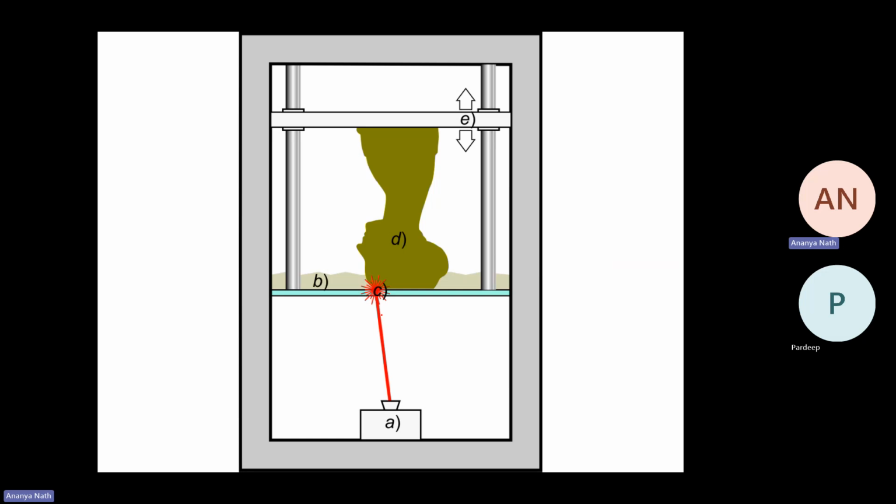It's similarly a light source, curing the liquid resin, which is present here. You can see this is the build plate, and the build plate is mounted vertically upside down. So my model is getting printed vertically upside down. But when we turn it straight, when you take out the build plate, your model will be ready in its original direction only. So this is called stereolithography, SLA, which again comes under the state of the art of VAT photopolymerization.